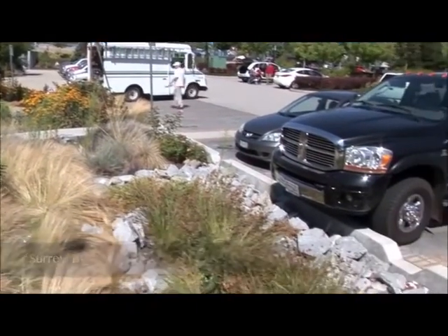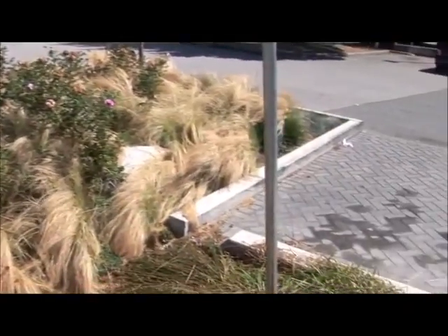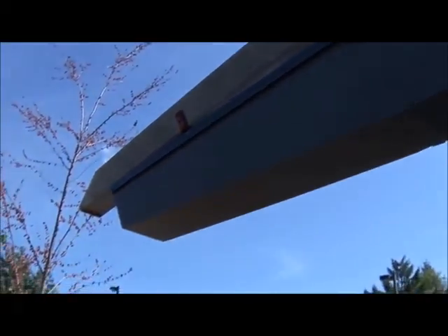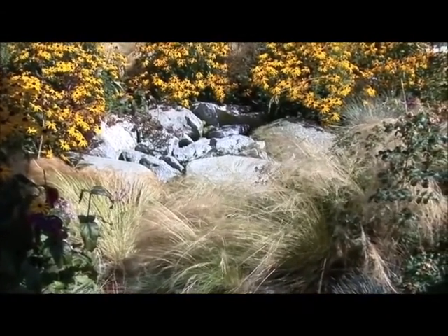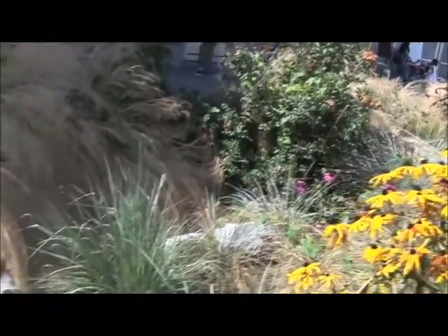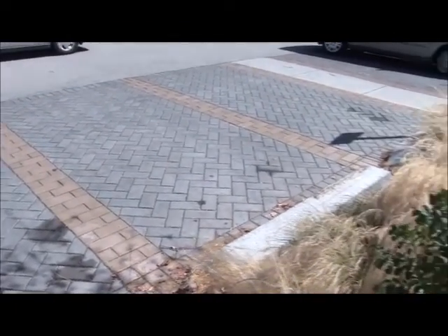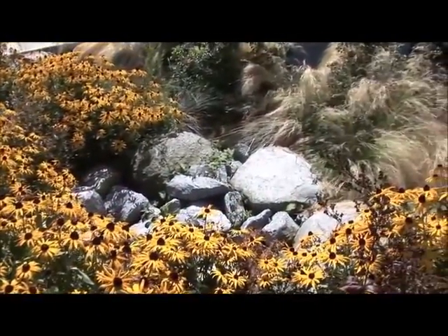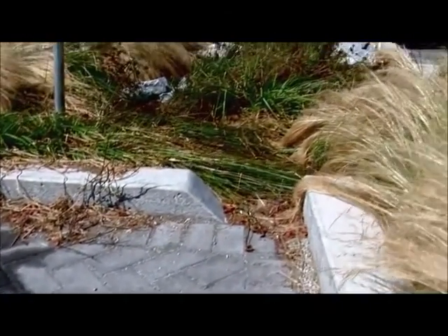These designs are not only found on houses. Even your local community center can incorporate stormwater management into its landscaping. The South Surrey Community Centre has a specially designed roof that directs roof water down a spout into a rain garden. Rain gardens create seepage areas where water can infiltrate into a grouping of plants called an artificial bioswale. Concrete pavers on the parking lot allow some water to infiltrate into the soil below. The soil then treats the oil and grease left behind from cars. The parking lot is also graded to coax water to flow into the rain garden.